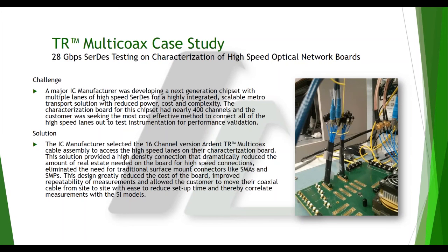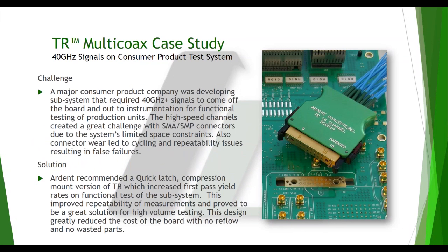So the next application is one I touched on a little earlier, where the customer had several boards, several systems they wanted to test. They didn't want to keep connecting their connector to their VNA over and over again, or snapping and unsnapping SMPs. So they bought a quick latch. And you can see the quick latch cutouts next to the footprint there. One is larger than the other, so you can't put it on backwards. Also, the guide pins do the fine alignment. The latches just do the rough alignment. And like I said, it compensates for all your varied thickness in boards.